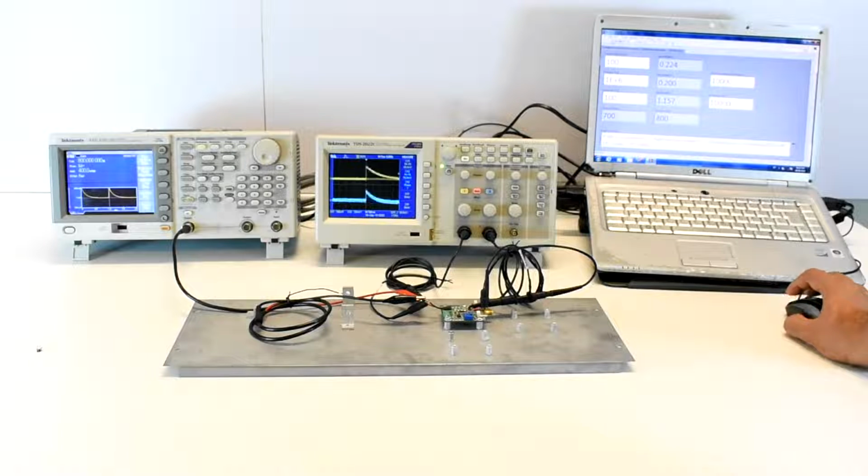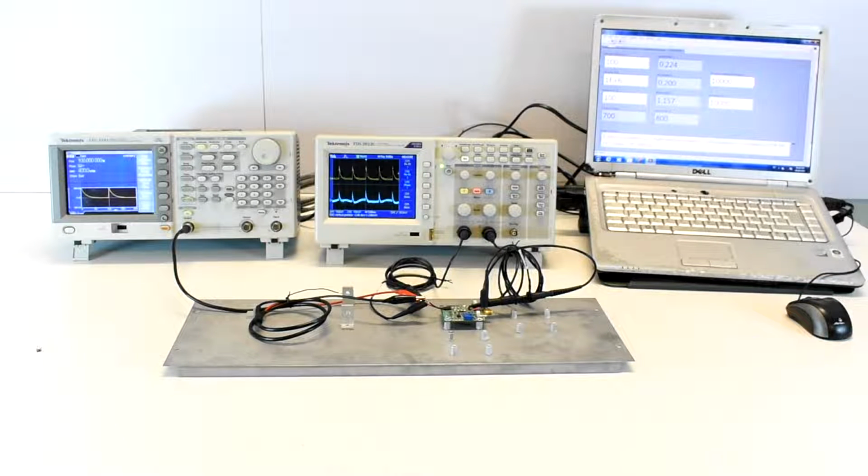The following actions are performed by LabVIEW. The program starts sending all setup instructions to the function generator and oscilloscope. Enables the 50 ohm output connector of the function generator. Awaits 8 seconds. Instructs the following oscilloscope measurements.